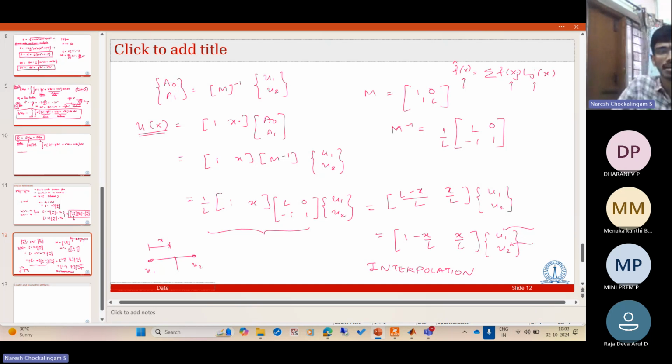So starting from the nature of the strain, we said it has to be constant, so the displacements have to be linear. And if it is linear, it has to be related to the end displacements. And the relation is actually this. These are called the interpolation functions or the shape functions, and let me call this just N U. Let it be whatever it is.